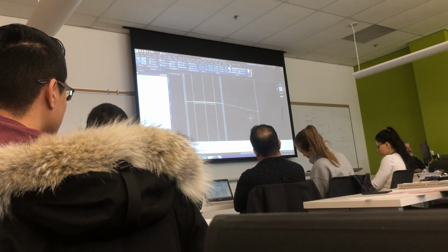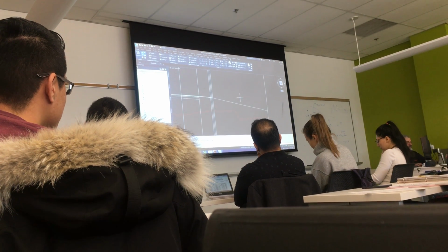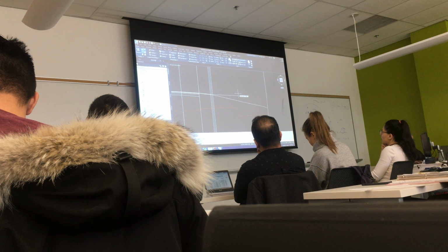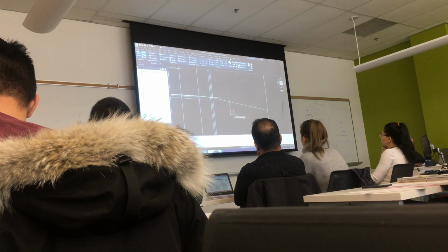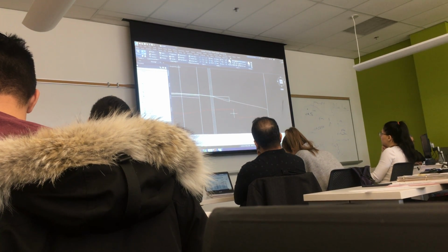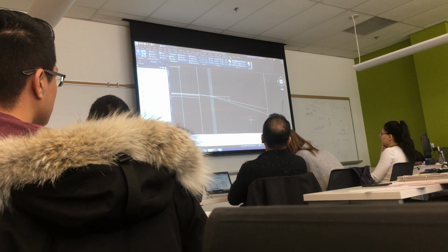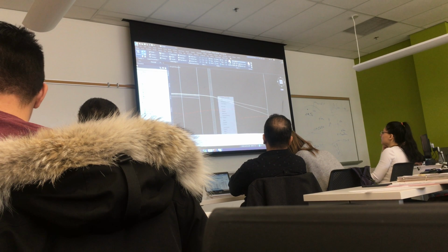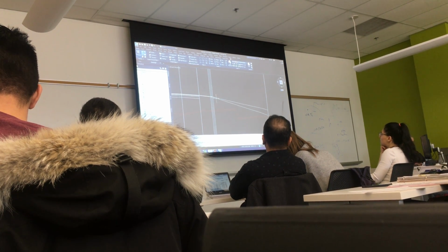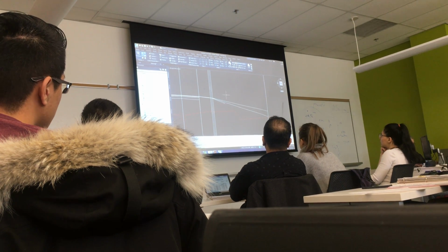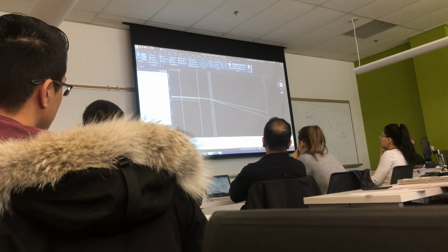And it looks like it wants to be a fill. So let me try, instead of a 6 to 1, let me try a 4 to 1. So I'm going to draw a line from the same point. I'm going to go 4 and down 1, and then close that and extend that. That's still no good. Okay, let me try something steeper. 3 to 1. 3, 1, close, extend. Gonna hit one of these.